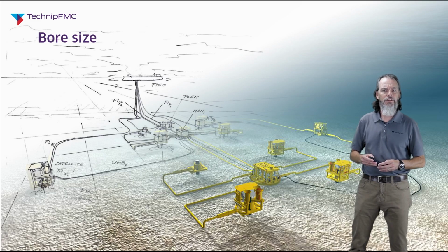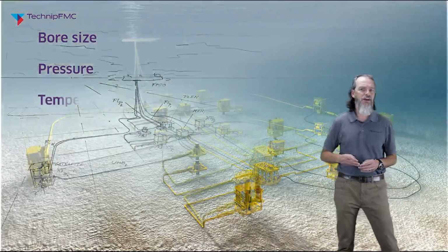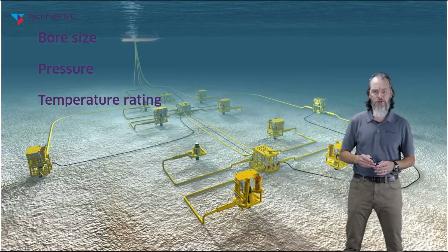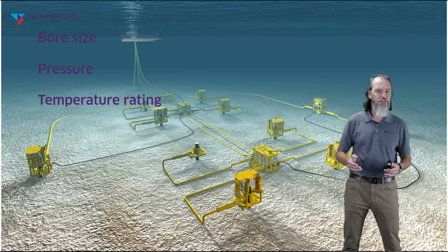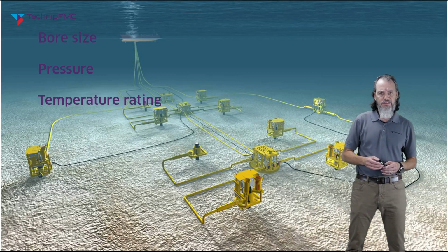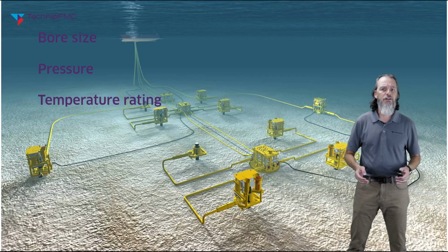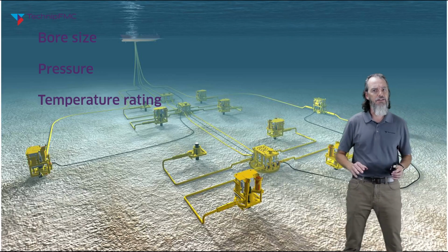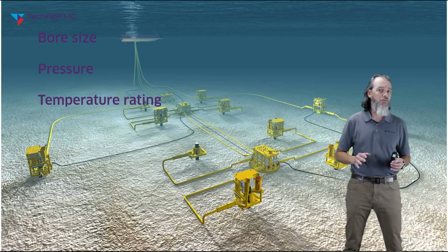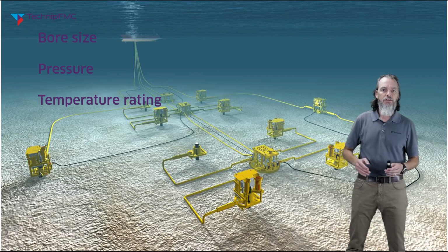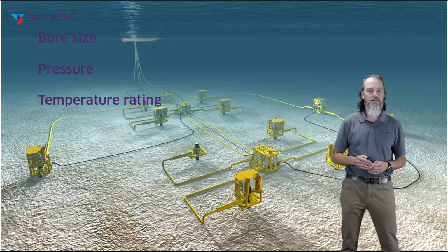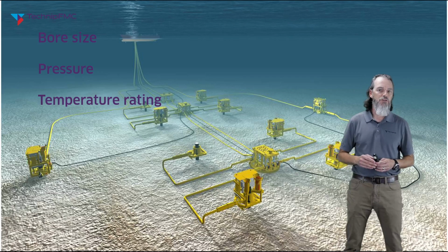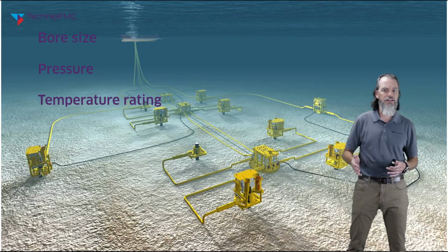It's also important to note that the industry standards do not define the functional requirements for each piece of equipment. Things like bore size, pressure, temperature rating. This is left to the operator or the system integrator, whomever is responsible for the system design to define. There's a significant amount of FEED work, front-end and engineering design work, required to establish the system design and functional requirements, which would be compiled into a basis for design document.